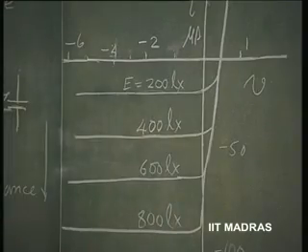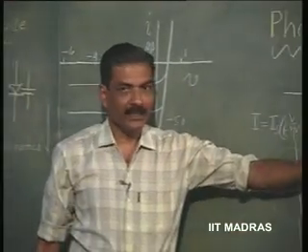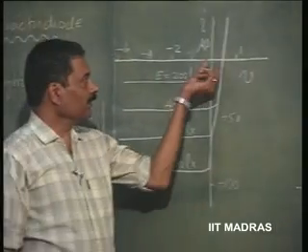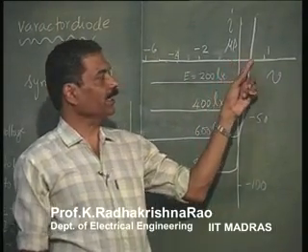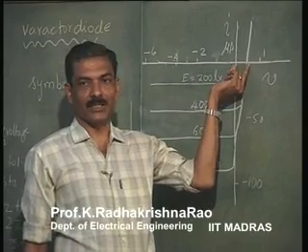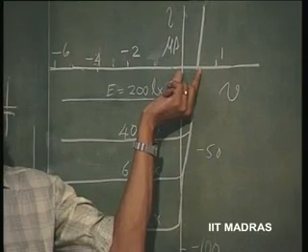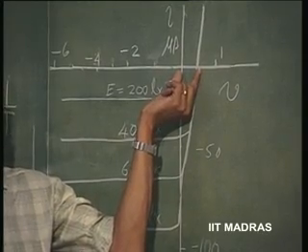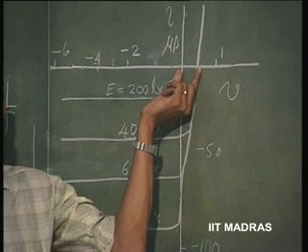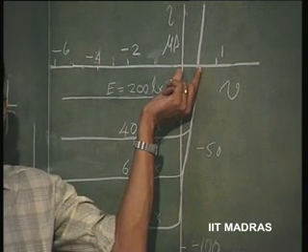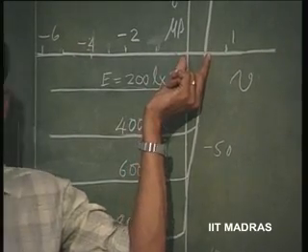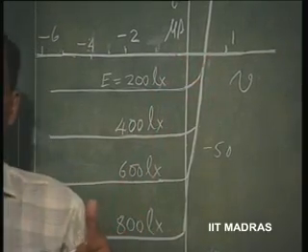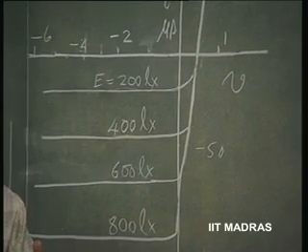Not only that, because it can be sustained like this, it is going to have an open circuit voltage, because this current is 0. If the intensity is large enough, this open circuit voltage gradually goes towards the 0.5 value for silicon. So, this is the open circuit voltage, and therefore it can be used as a voltage source, a battery.